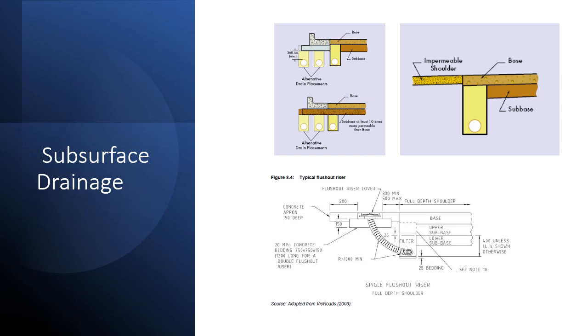Having a proper outflow for the subsoil drain is very important to make sure it is functioning well. So in both cases, connecting either to the stormwater pit or to the open channel is to ensure that the subsoil drain is draining properly.